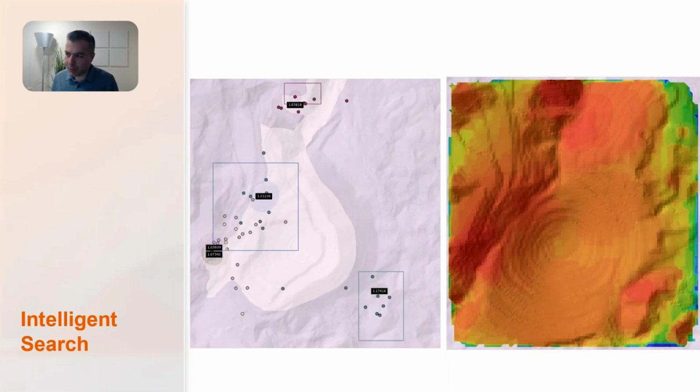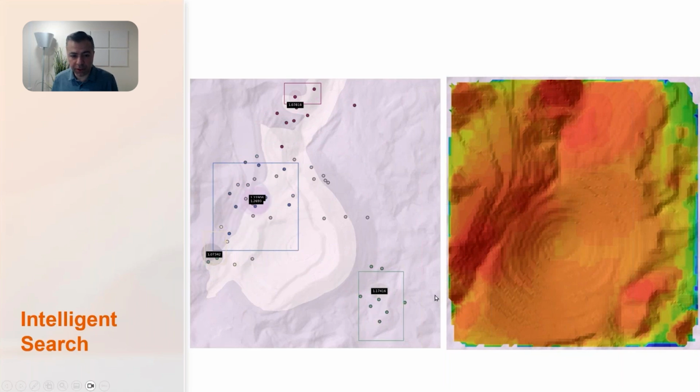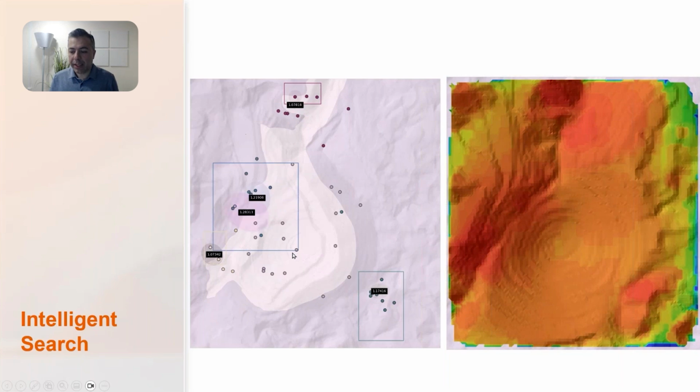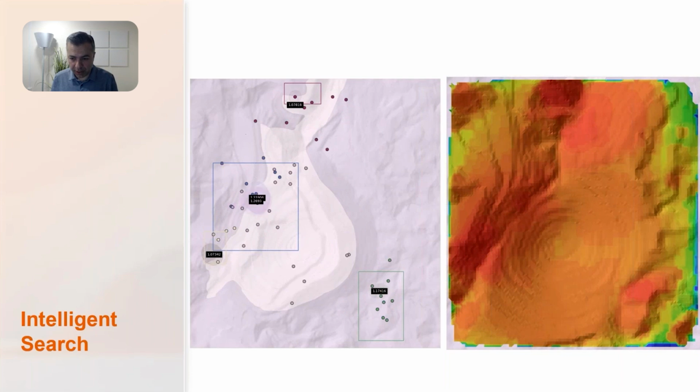And you can see how these particles move around and they find the lowest factor of safety. They are focused on different regions to find the local factor of safety. And you can see the safety map here that shows the critical regions, which are the red regions, and safe regions. So this is a game changer, basically, in terms of searching for the critical slip surface for 3D models.